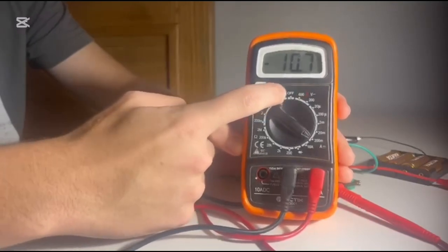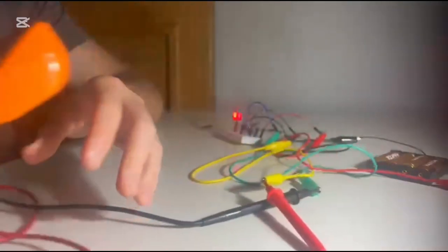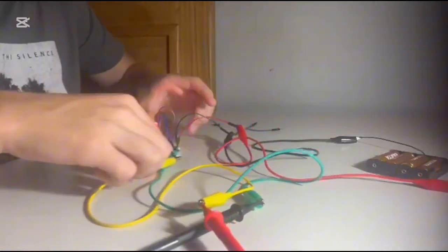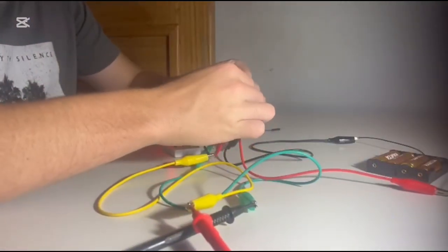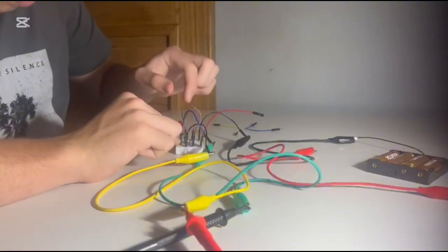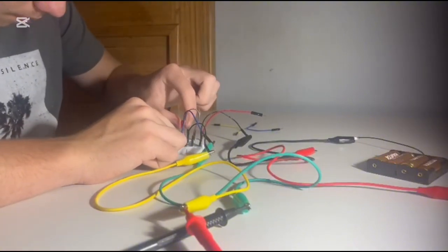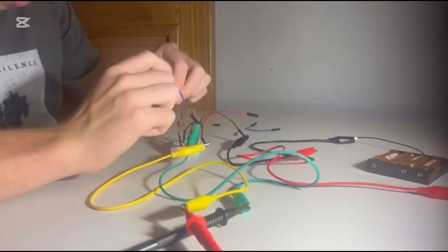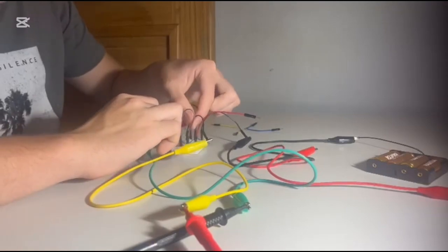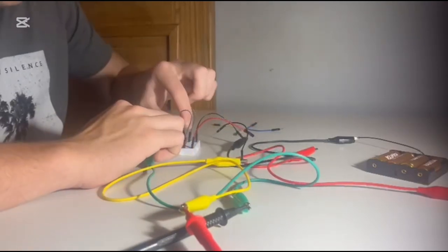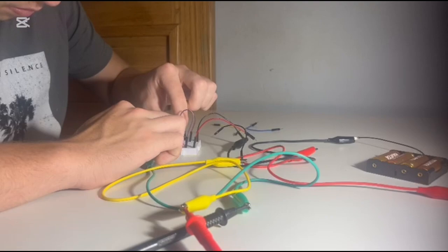Now we will remove the ammeter from the circuit, replace it with a lead, and reposition the ammeter between the second LED and the voltage source. An ammeter has very little resistance, and so we place it in series to measure the current flowing through it and the rest of the circuit.